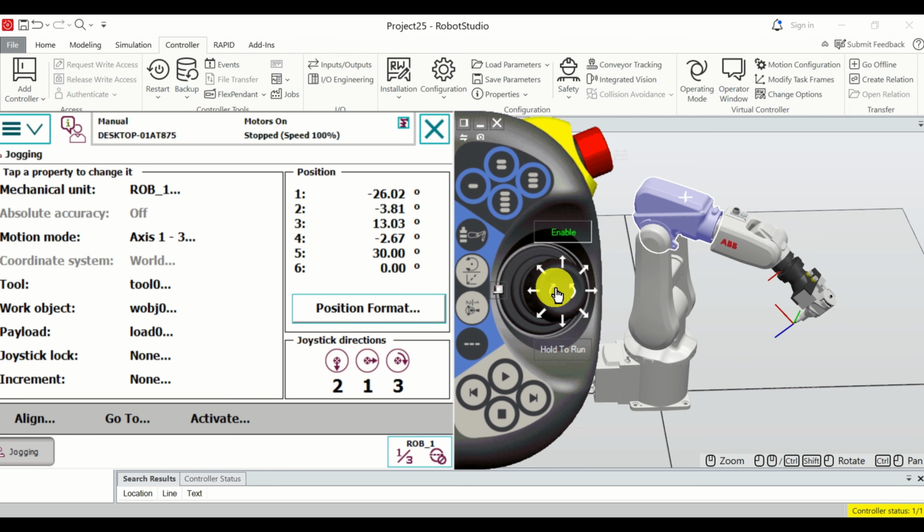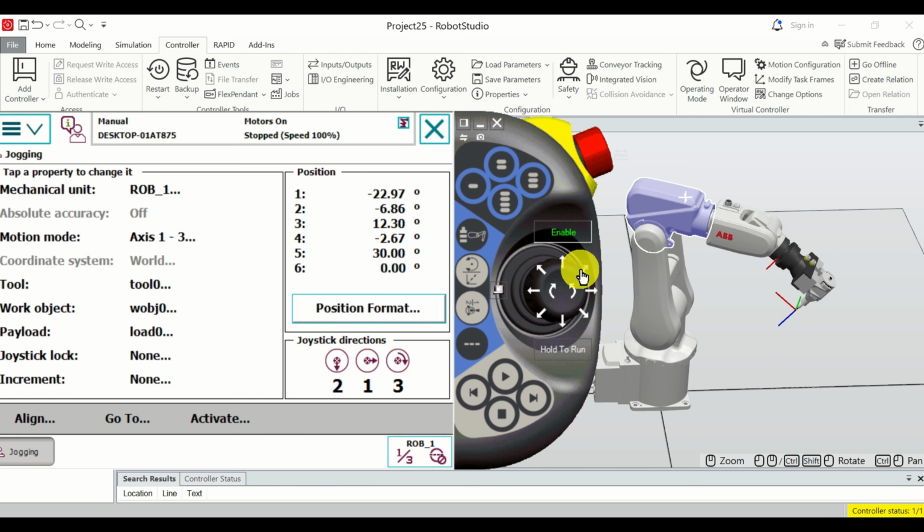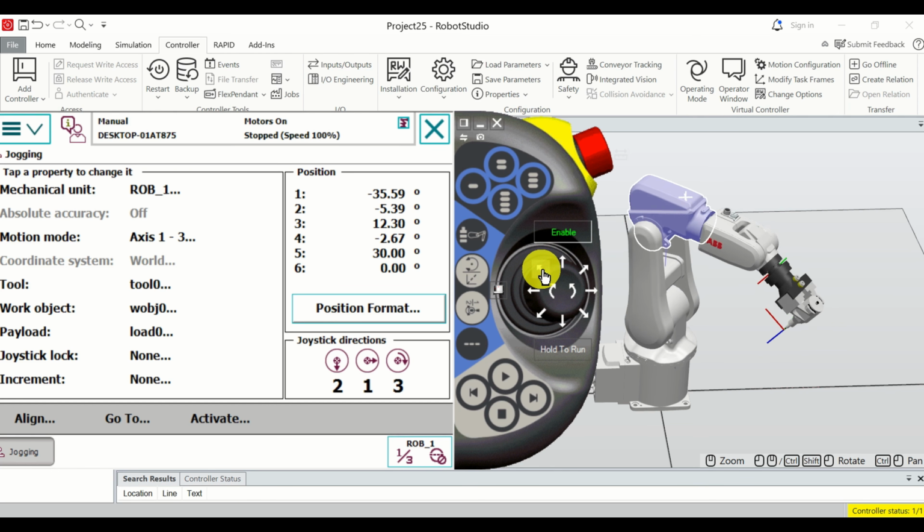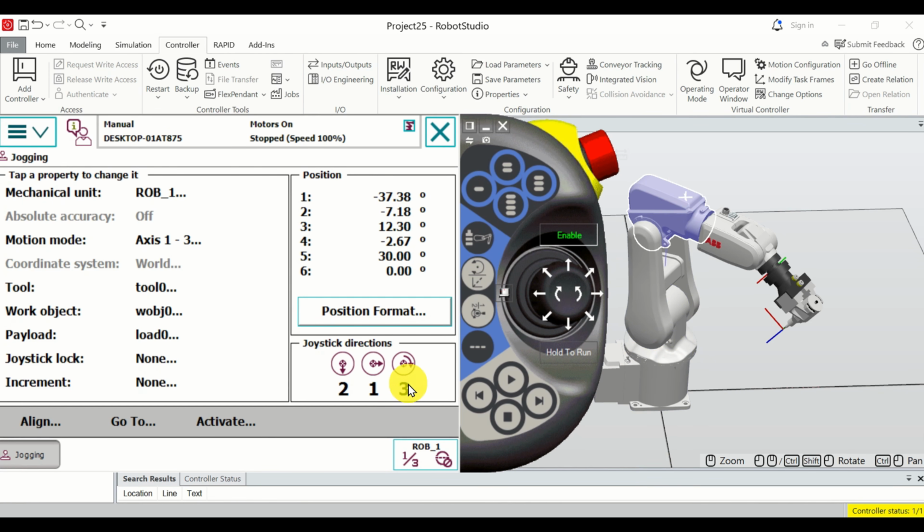And the same thing applies to your robot. Then, if you, for example, move the joystick in this direction, you will have a combination of several modes, as you can see over here. Or over here, you can see also a combination of several modes of motion. Now, what is very important to observe is that over here you can read the angles of your joints. You can see the first, second, and third one. These are the angles measured by the absolute encoder that's installed over here near the motors. So over here we can only move the robot around the joints 1, 2, and 3.